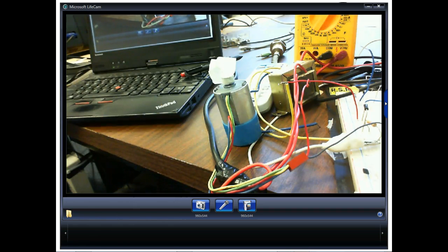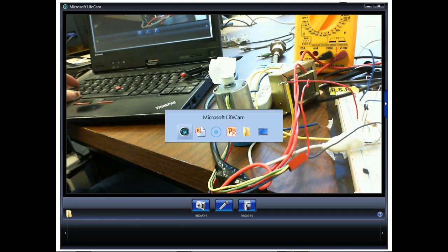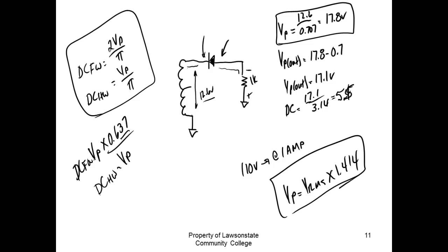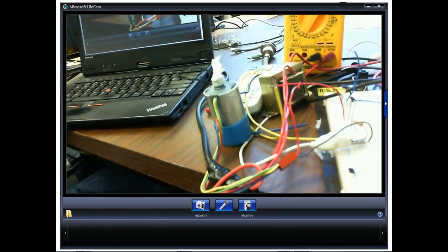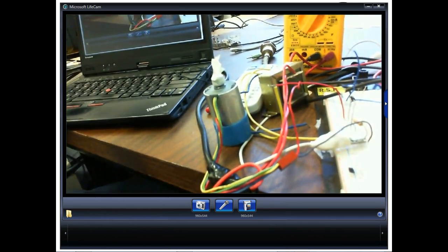What you're doing is you're trying to put the diode in a DC circuit. This is not a DC circuit. So what's happening is that my AC is coming in here, so the diode is going to be forward biased on one of these alternations. It's just now forward biased on the negative alternation. Okay, you understand. I come up here and flip this around, all our calculations are going to be exactly the same. So what you're seeing, Larry, is not a DC circuit, it's an AC circuit.